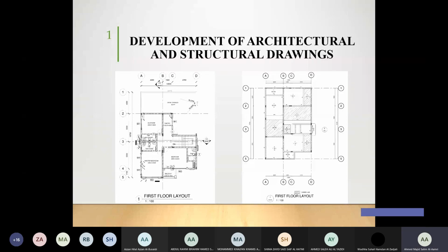Okay, it's going to be suspended. If it's suspended, it means the load will be there. It is going to bend, it's going to deflect. So in order to solve the problem of bending and deflection, we need to provide the appropriate reinforcement. In order to provide the appropriate reinforcement, you need to design it. That's why we design the floor. We design the first floor, second floor, and it goes on. We don't design the ground floor unless it's a basement.